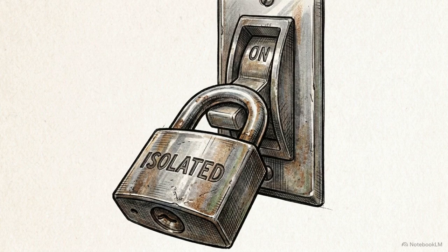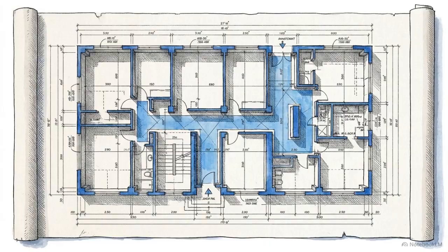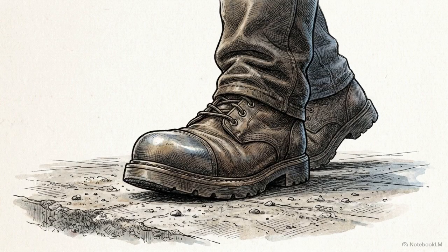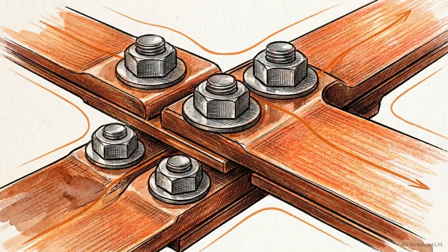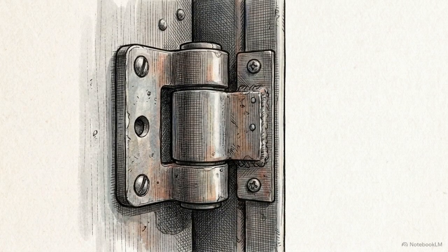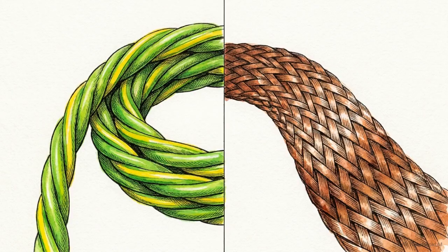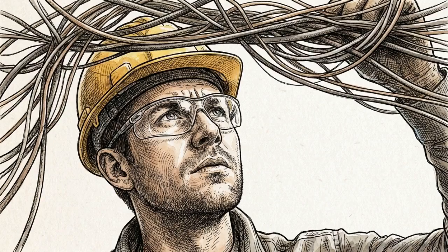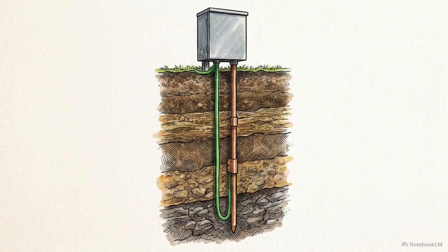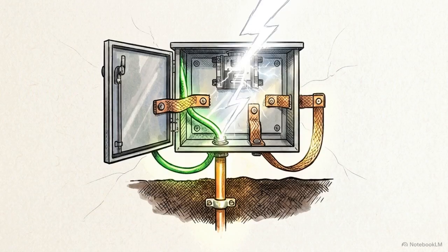The theoretical architecture of the diagram eventually translates into the physical reality of installed metal and copper and thick electrical enclosures. Securing this physical equipment requires understanding the distinct difference between grounding and bonding, two terms that engineers frequently confuse, despite them serving entirely different safety functions. Grounding is the physical connection linking the electrical system directly to the earth via a rod. It provides a safe, direct clearing path for catastrophic electrical faults.